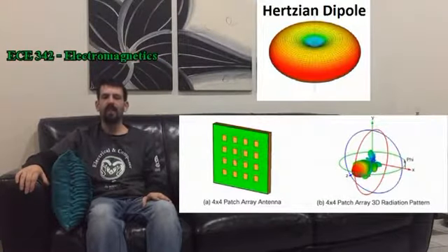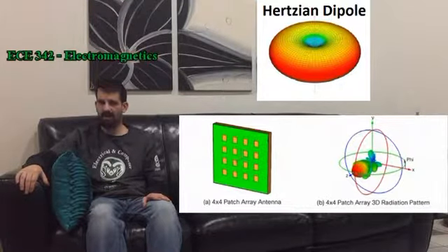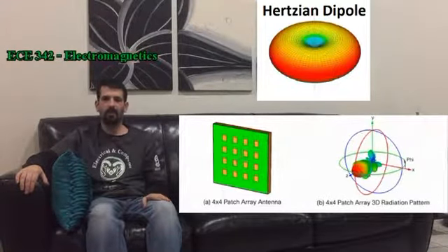The shape of the antenna also dictates the radiation pattern and which directions the signal is strongest in, as seen here. Regardless of the shape, the size of the antenna has to match the frequency of the signal that it is transmitting. Higher frequencies require smaller antennas, and lower frequencies require larger antennas. Antenna size is directly proportional to the wavelength of the signal being transmitted.